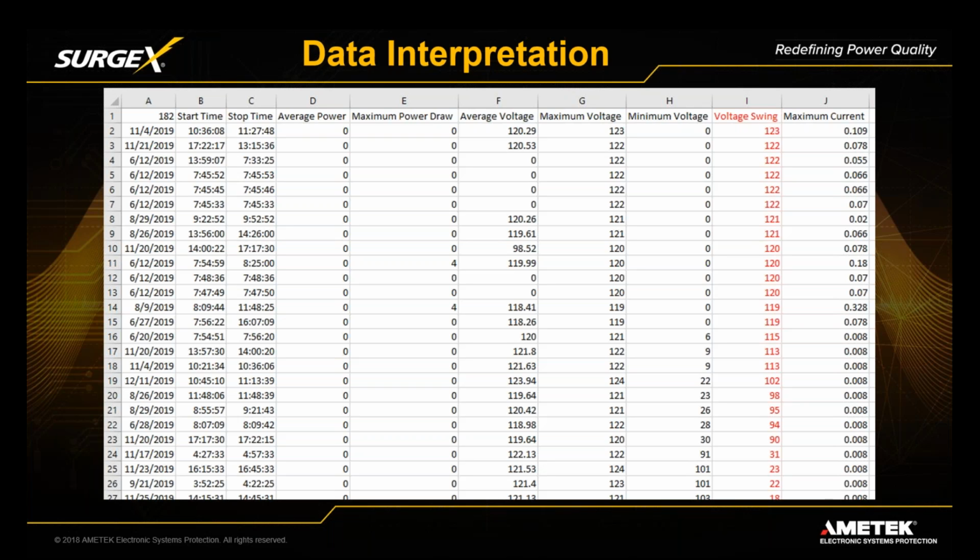If you can imagine, if you were storing data every 3 AC cycles, remember, 60 hertz means 60 cycles per second. So that would have been, you divide that by 3 cycles, every second having 20 times the 5 or 6 values. It would be a huge amount of data, right? So this is a way to compress the data and still have it be very, very useful data.